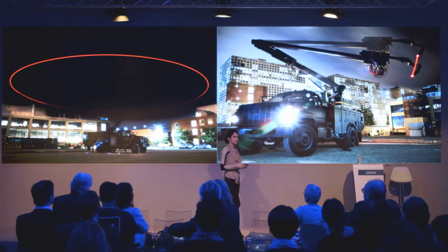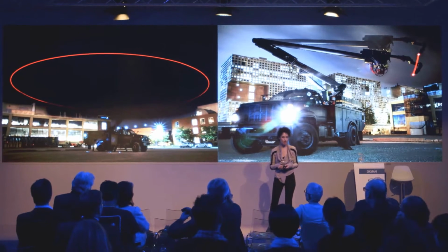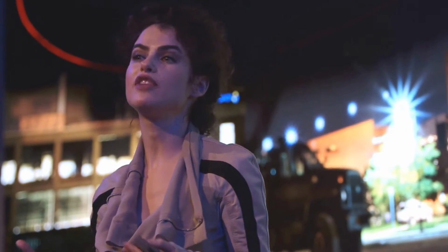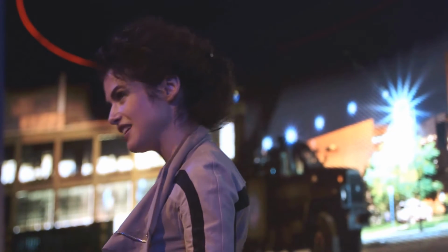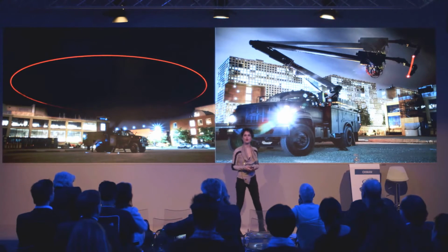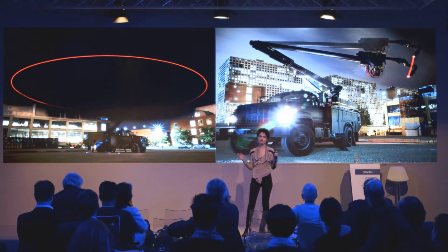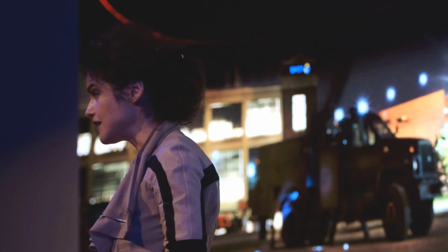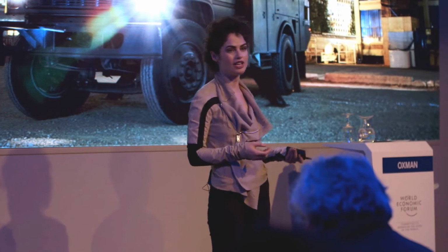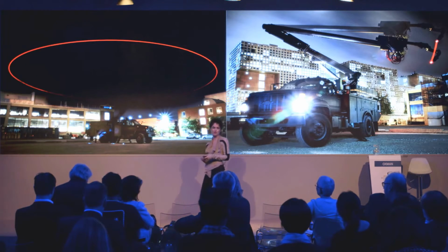So this is the first robotic system that's completely mobile. It's called the Digital Construction Platform. And it is a platform that is designed to additively manufacture a building, hopefully in a single day, on site, continuously as the printer goes about the site. This is a long exposure photograph just to show you the range. This is an 80 feet diameter range for a large-scale robotic arm, a hydraulic arm that's connected to an electric arm, 5 and 6 degrees of freedom that allow us 11 degrees of freedom on site.